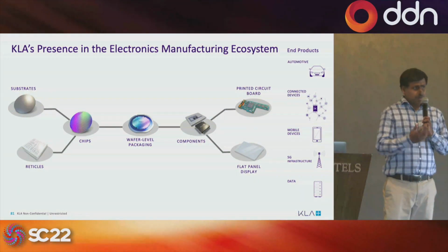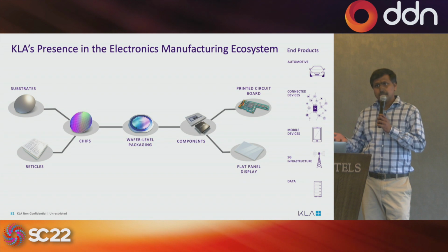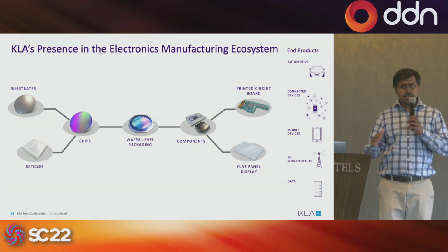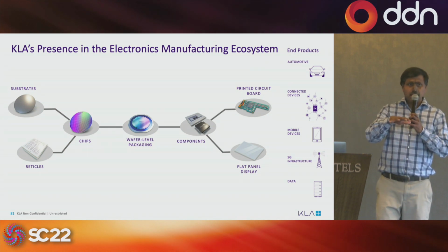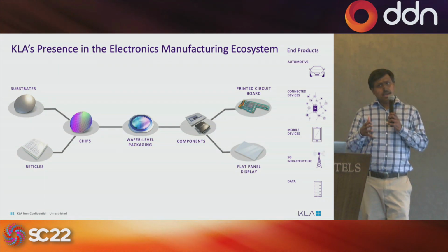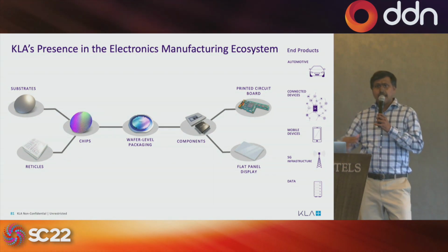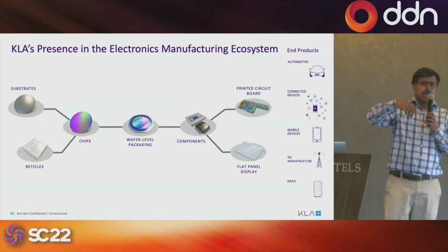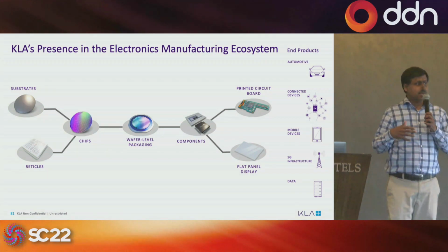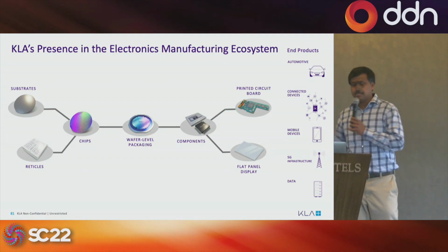If you're familiar with the semiconductor build process, then yeah, it's good. But if you're not familiar with it, basically what they do is they start with the silicon substrate. They have the reticles or masks using which they make layers upon layers, and for making a single chip they go through roughly multiple hundreds to thousands of process steps, wherein they add material on top of material, they do etching, they cut the material out, they do various processes called lithography, multiple hundreds of steps to get to the final chip.